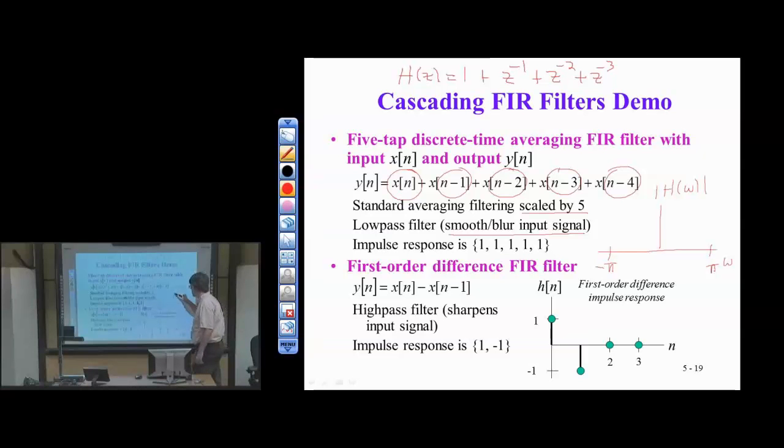And in the frequency response, this is going to correspond to 2 frequencies being removed or zeroed out. And then the value at the origin is going to be equal to 5. Again, to convert from the Z domain to the Fourier domain, we take the Z transform and substitute Z equals e to the j omega. So at omega 0, this corresponds to Z equals 1. So a way we can read off the DC response of this filter is simply let Z equals 1. So omega equals 0 implies Z equals 1. So in the Z plane, the value Z equals 1 is the 0 frequency point. Again, that value will be 5 if we let Z equals 1 and plug that into the transfer function.